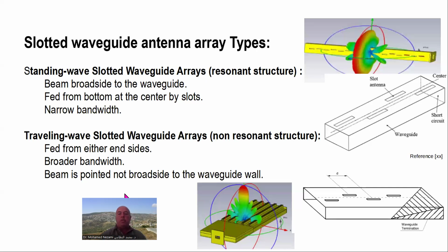It has to do with the fact that for your waveguides, you either do a short on the end, and the placement of the slots is a half wavelength from each other, uniformly spaced, and at a half wavelength from the feed point, okay? In that case, this would be a standing wave array antenna because the waves just reflect in here and come back in phase, everything is constructive, so it's pretty consistent.